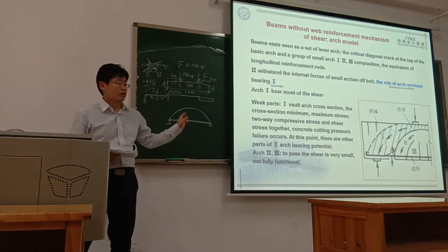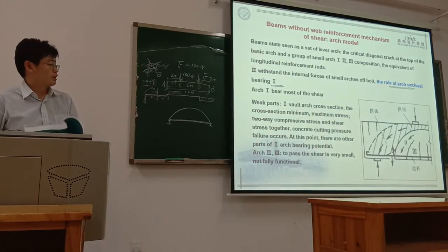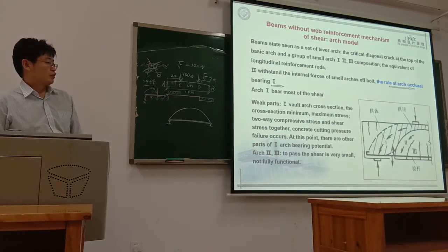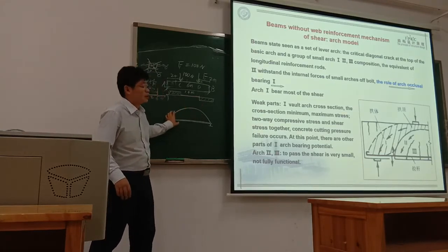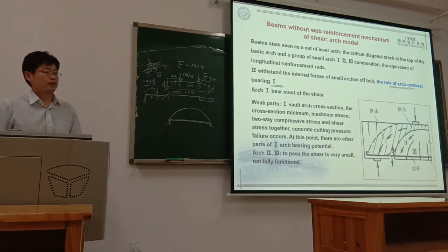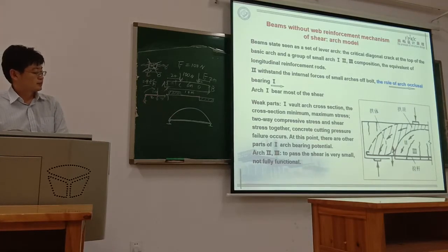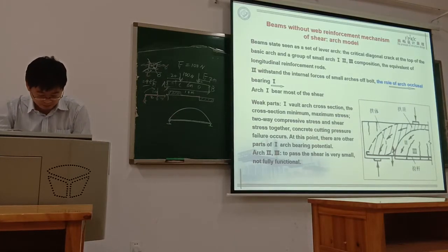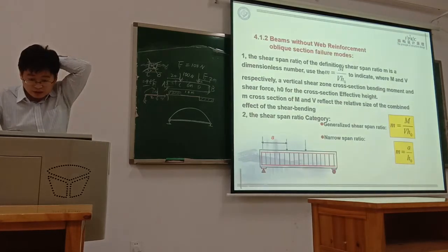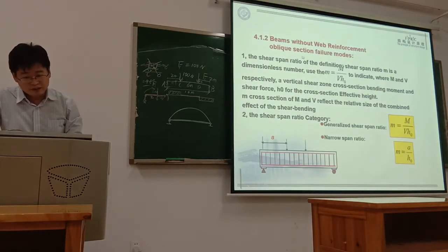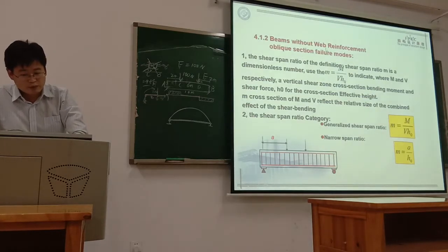So the force system for this beam without web reinforcement works like this tied arch. So we see the failure mode of this beam without web reinforcement.